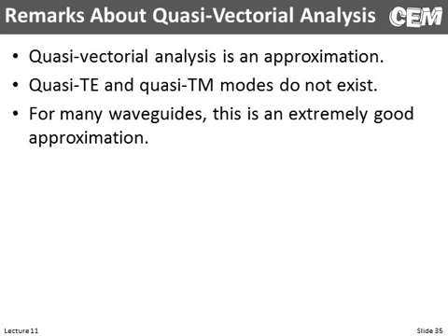So I want to leave you with this. Quasi-vectorial analysis is an approximation. TE and TM modes do not exist in channel waveguides. So we're going to call them in this class quasi-TE and quasi-TM. But hopefully in these slides I have justified that it is a very good approximation.